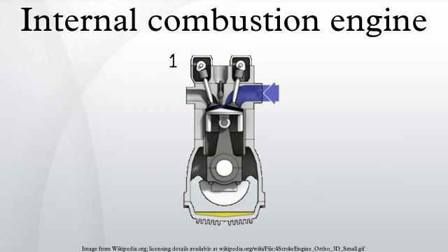At the time the transfer port is uncovered, the compressed charge from the crank chamber enters into the combustion chamber through the transfer port. The fresh charge is deflected upwards by a hump provided on the top of the piston and removes the exhaust gases from the combustion chamber. Again, the piston moves from bottom dead center to top dead center, and the fuel-air mixture is compressed when both the exhaust port and transfer ports are covered. The cycle is repeated. Advantages: one, it has no camshaft and valve mechanism, hence simplifying its operation and construction. Two, one power stroke for one complete revolution of the crankshaft.